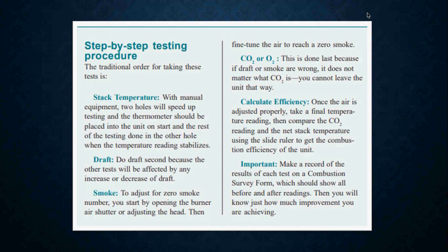So say, for example, you are reading a stack temperature of 400 degrees and you are in a room that is at 50 degrees. 400 minus 50 is 350. That is your net stack temperature. You are going to base your readings off of that temperature.